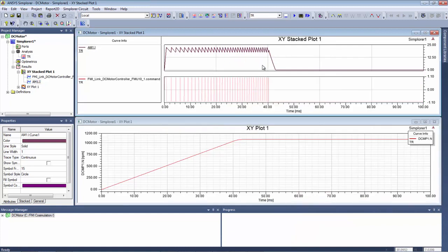And the regulation goes on until the regulation speed is reached. So this is what you can observe here on the plot of the rotor speed of the machine. And this waveform, this behavior is actually expected since we haven't put any load on the electrical machine.